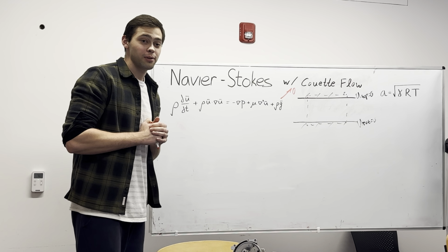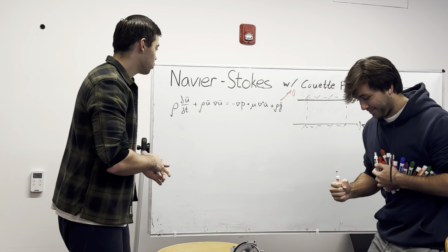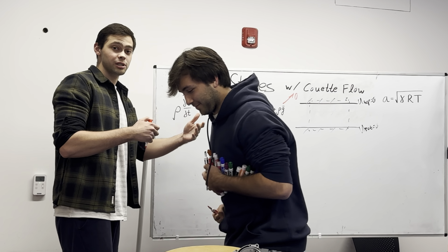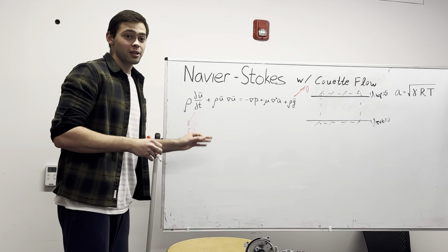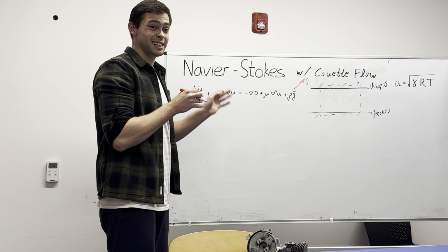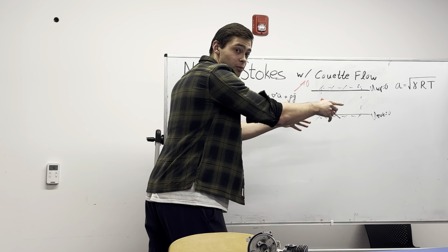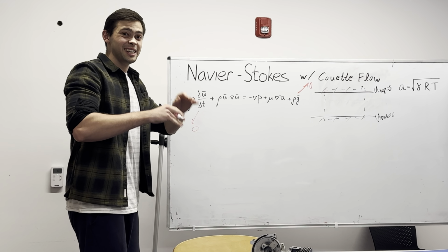Well, first of all, since we are dealing with a developed flow far away from the boundary, it is in a steady state. So our acceleration term, that is the velocity change with time, goes to 0. Now let's look at the momentum flux term. Well, first of all, we know that the velocity is the same on the inlet and the outlet of our control volume, which means that the momentum flux into the system is 0.